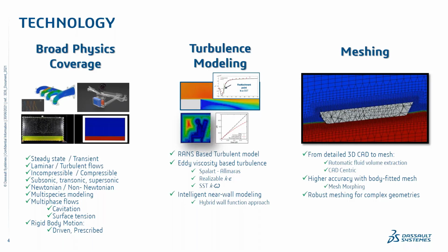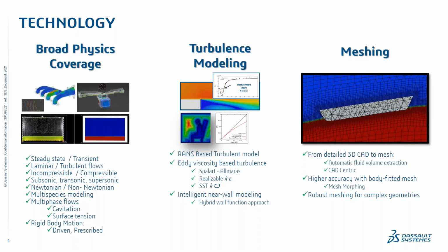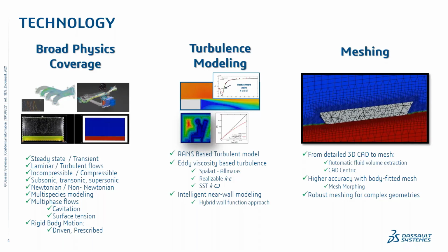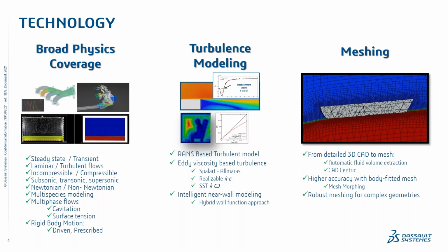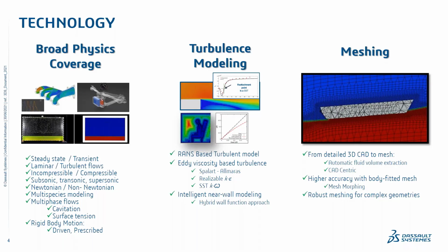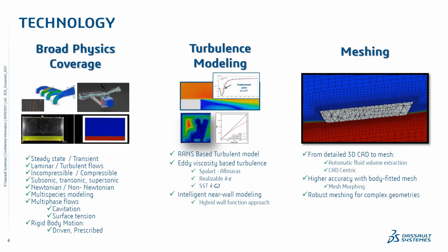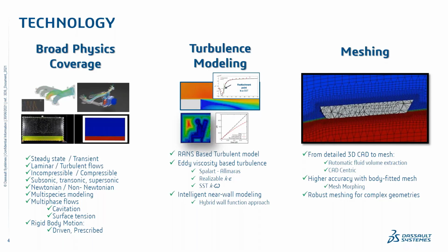The other technology is the meshing process. We use a body fitted mesh, which, if you think about it, is a hex dominant mesh, mostly used for meshing the fluid domains. But that's the dominant technology that we use; there are other meshing techniques also available if you have a need, such as a sweep mesh, a tetrahedral mesh or a surface mesh, whatever the case might be. You can mesh your fluid regions with different mesh options.